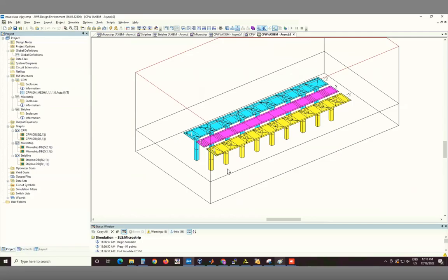But in small chips, like the ones we make for our superconducting experiments, where we also make resonators and transmission lines, we don't want the same problem to happen there either. But those are made on either silicon or sapphire, at a much smaller scale. So with a 10 micron gap, you can't drill holes in a mechanical way. There are chemical ways of doing that, but typically, instead of going through the substrate, which is harder to do, you go above the substrate.